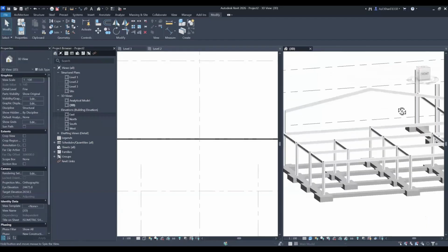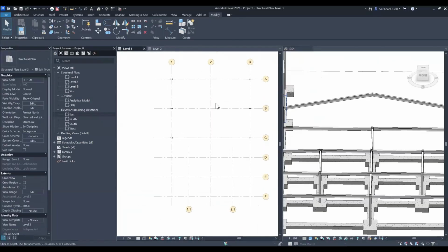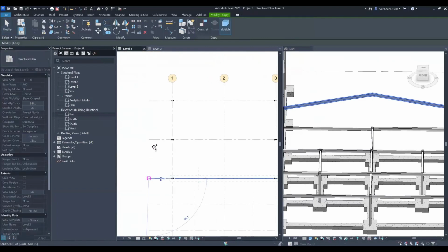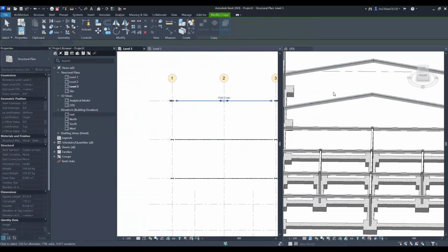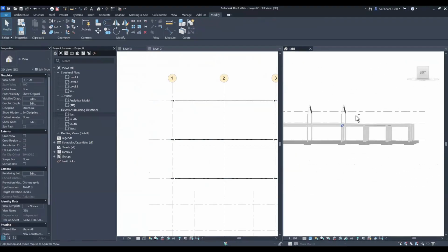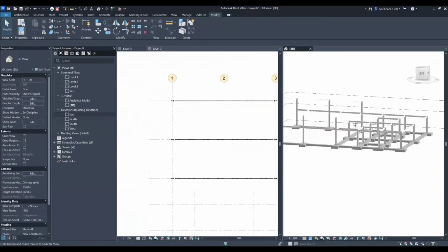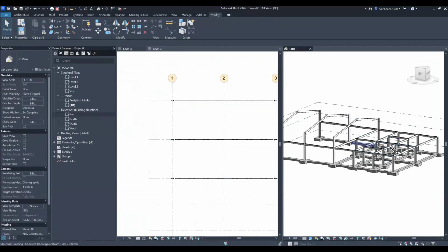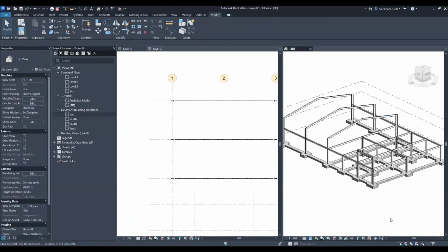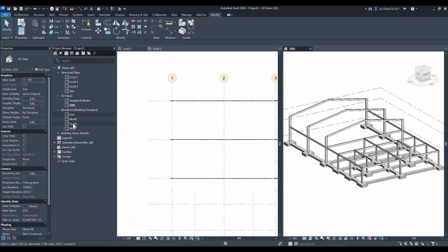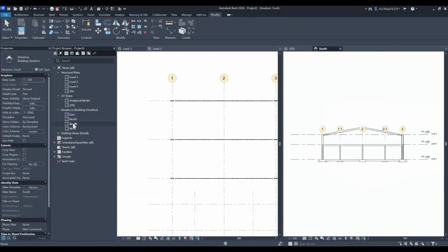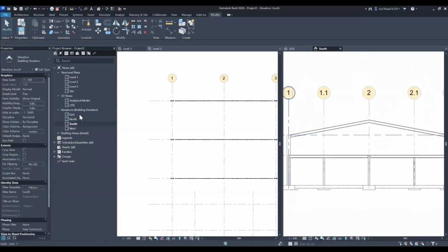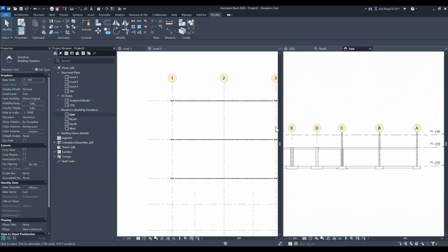And I'm so happy about what I get. Now, as you can imagine, I'm definitely going to copy this, select these 2. I'm going to take my copy tool, this end to this end to this end. There it is, my industrial frame plus my flooring system. Say this is a part of an industrial building, some sort of facility, and that's done within just a few minutes. And if you remember, our elevation drawing is already prepared without any extra line work. I can go to a different side view, and as you can see, it's already done.